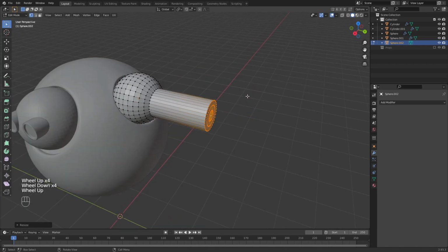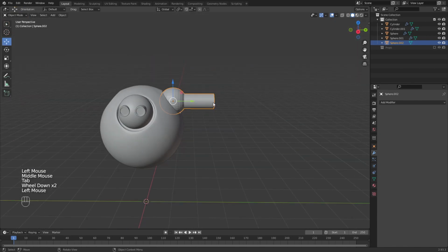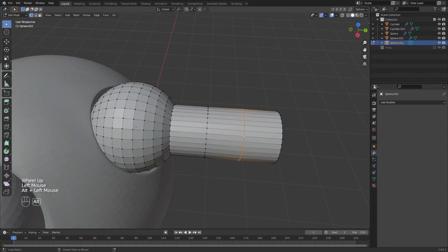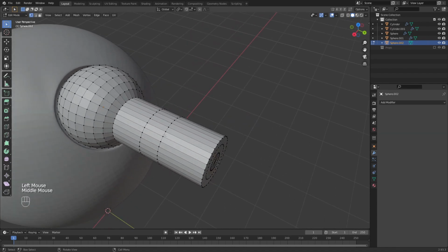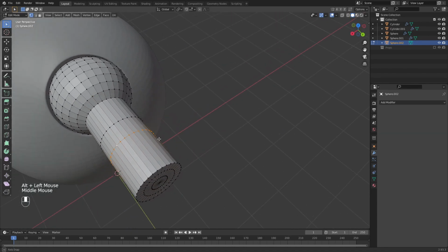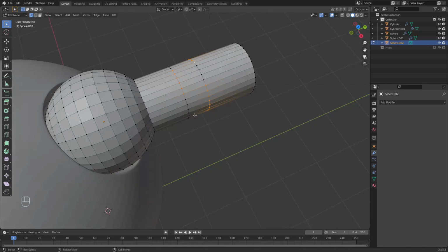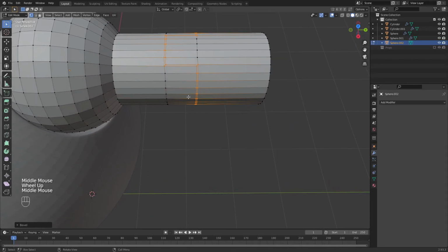And the arm looks a bit plain right now, so let's add a cool design. Tap into edit mode and add 2 loop cuts and move one of the edge loops closer by selecting it and double pressing G and then just dragging it. Selecting the whole edge loop and then these few vertices and then select these other ones right here, like shown. Now bevel the selected vertices with only 1 cut and by pressing Alt E, extrude all the faces along the normals.